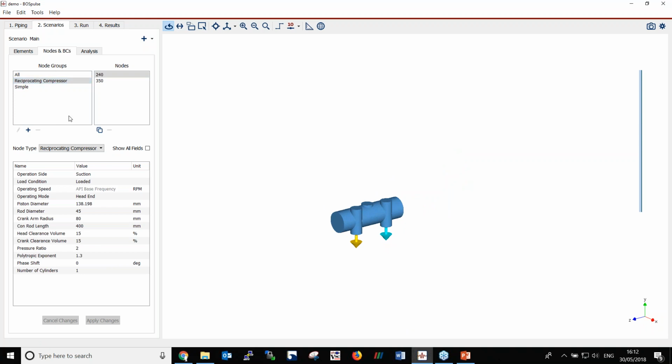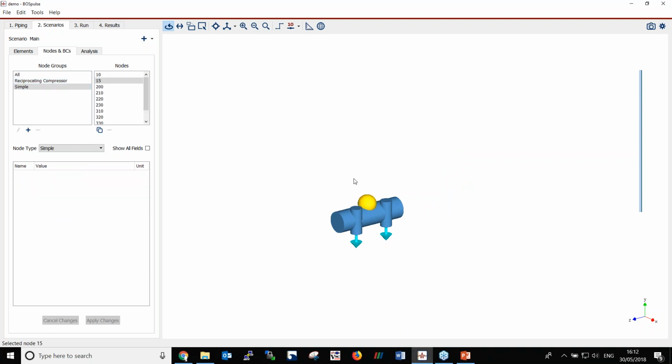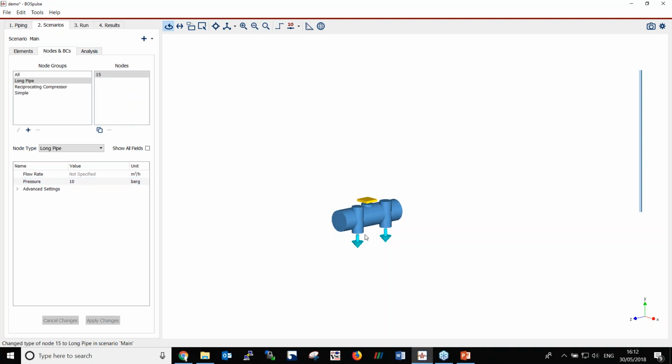Before we continue, I'm just going to show you something we fairly often do before we start a simulation. We're just going to look at what our boundary conditions look like. So we're going to add a long pipe boundary condition, or an anechoic boundary condition. That means no reflections from this side. This is useful, since we're not interested in acoustic resonance. We're just going to look at what our boundary conditions can do. So we've set it up, and this is a system we can run now.